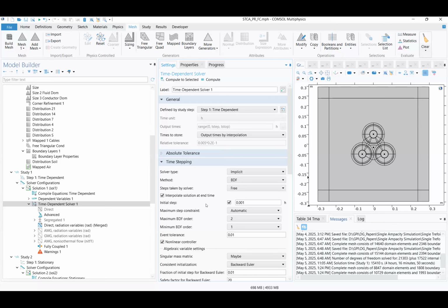So what you're saying is, if I have no idea, why wouldn't I have an idea? It's a physical problem, I need to have an idea no matter what. I can be wrong by orders of magnitude, but I need to have an idea of what my time constant is going to be. And if it is an LC circuit somewhere, you get the smallest L and the smallest C, and that gives you the fastest transient, and then you get the largest C and the largest L, and it gives you the slowest transient, right? So that's what I would do to at least try to bound it between something.